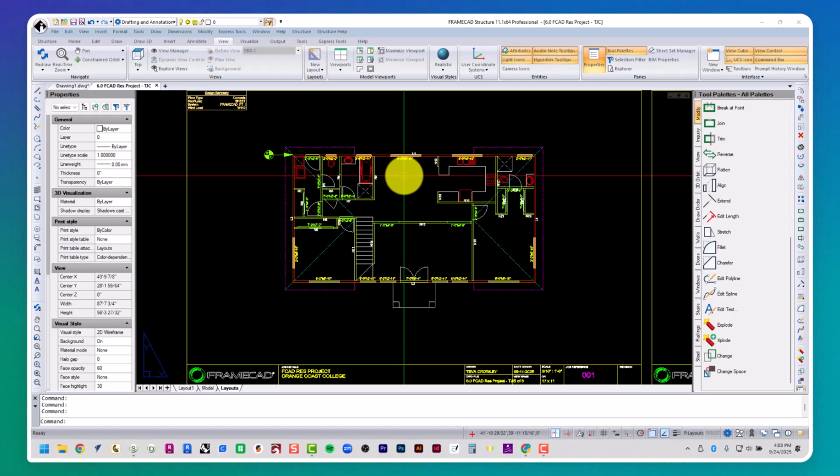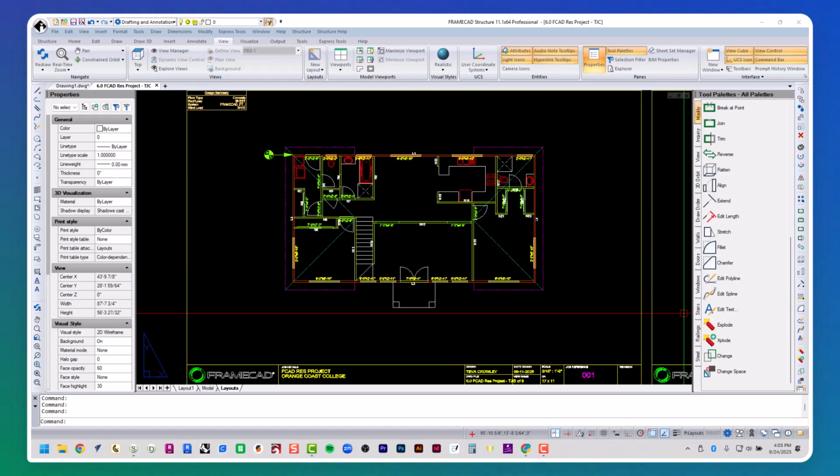All right, welcome back. This is 6.0 lower roof trusses. Today we're going to input our trusses, but before we can do so, we need to draw a polyline around the building to represent the external load-bearing support lines. This polyline will represent the truss's keel location or support line, and it'll be coded as a support line. We'll also learn how to add and code roof lines representing the eaves overhang.